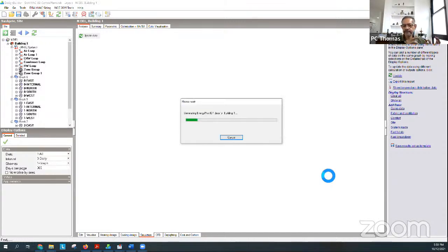And you can go and select different kinds of output. The more output you select, the more data you can get. So you will get the data broken down by chiller, by fan, by pump. You can get numbers for each of those outputs. And then you can look at the hourly outputs. In fact, the thing we might look at in the hourly outputs quickly is the two chillers, because we've scheduled the two chillers separately.